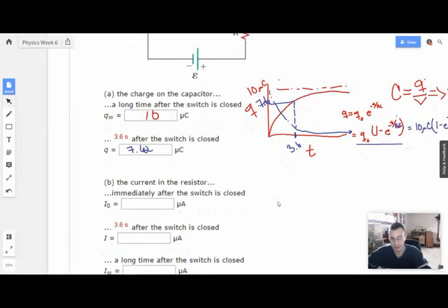So to do that in picture form, you have a pipe, you have your diaphragm, water pushes this way, it pushes the diaphragm that way, the diaphragm then pushes the water on the other side, and immediately, when it's at zero stretchiness to some stretchiness, it's not going to offer any resistance and it pushes the water straight to the other side. Eventually the diaphragm will become fully stretched, and this water will be just used to keep the diaphragm stretched, and it won't actually push any more water through the other side. So the way you model a capacitor at time t equals 0 is as a straight wire.